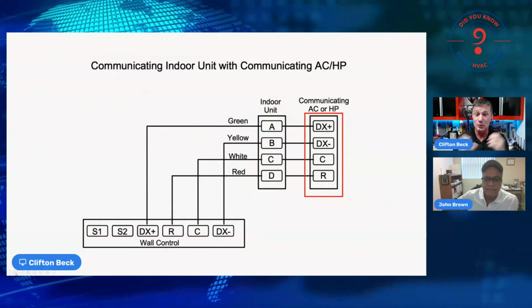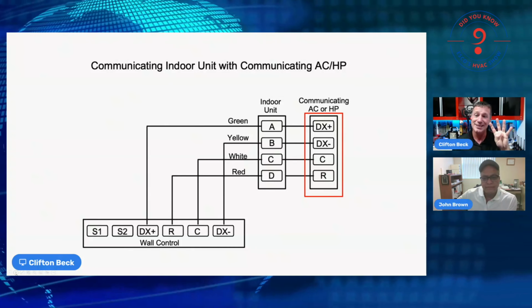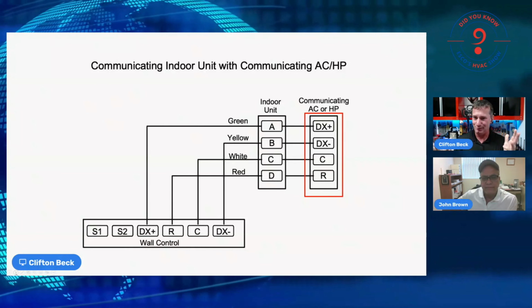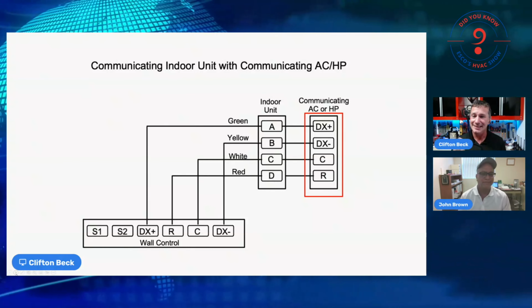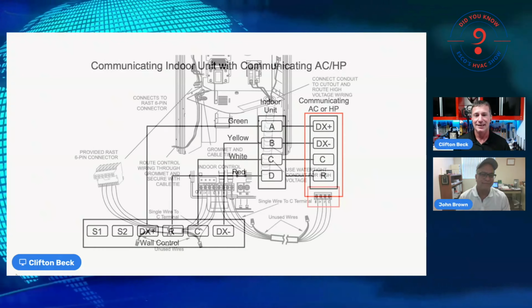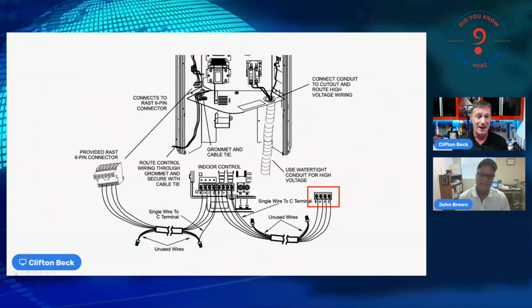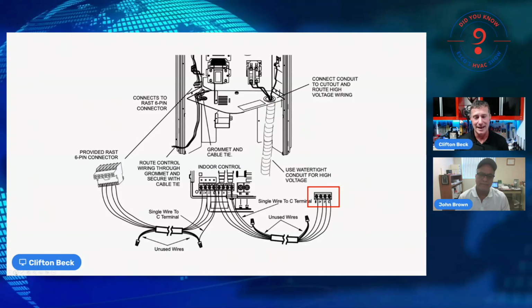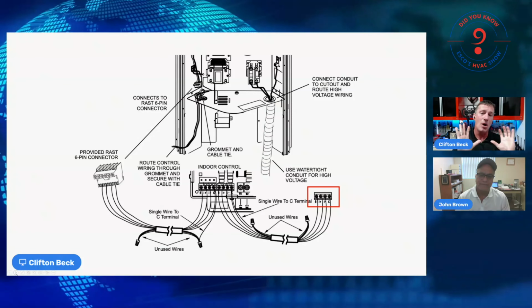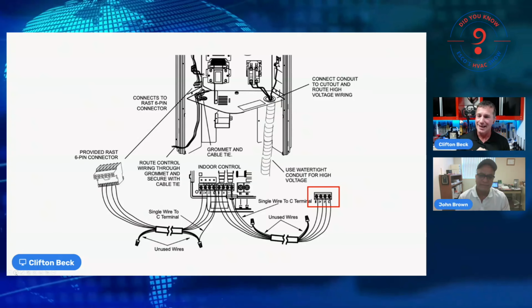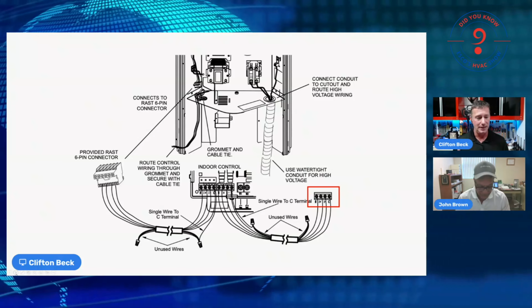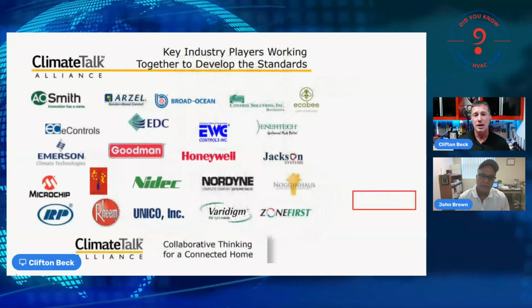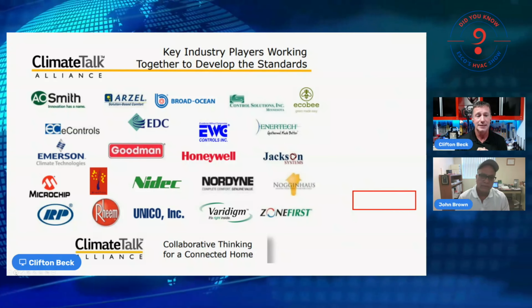If we look at this one, we're going to see a 4-wire connection. Two of those 24 volts AC and two of those labeled as a positive DC and a negative DC. So we look at this manufacturer, another reference of the exact same thing. I'm not saying that all manufacturers use the exact same, because I have seen some variations of it, but I will say that the philosophy, the technology behind it all comes from a similar design.